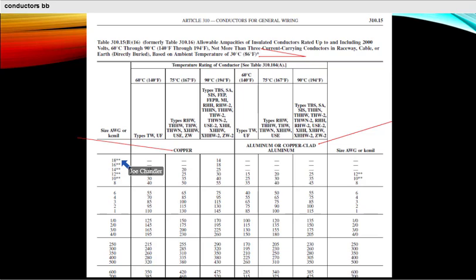But these are gauges of wires, AWG. So this is a gauge of a wire. And then we get to right here, 250 all the way to 2,000. That's the actual circular mil area, kcmil. Remember the K stands for 1,000 circular mils. So that's what that means. This is 250,000 circular mils. This is 400,000 circular mils. So these are our wire sizes.